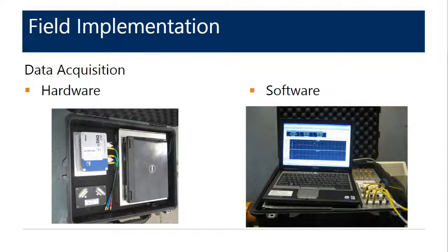The proprietary SOMAT data acquisition software, the TCE test control environment, is used to configure each recorded channel and is set to record at 50 Hertz. Note that this frequency is less than some of the other specified recording frequencies out there. However, it has been proven that 50 Hertz is more than adequate to capture the required data for operational strain gauge testing. The data acquisition software results in a file that is then processed in Excel.